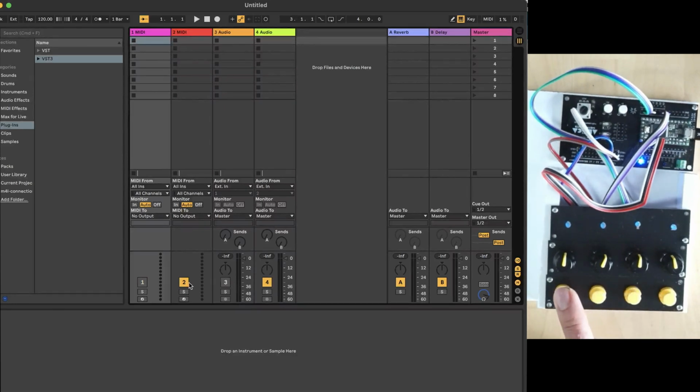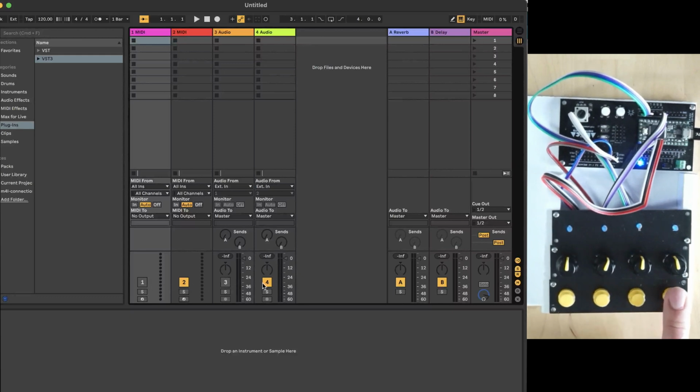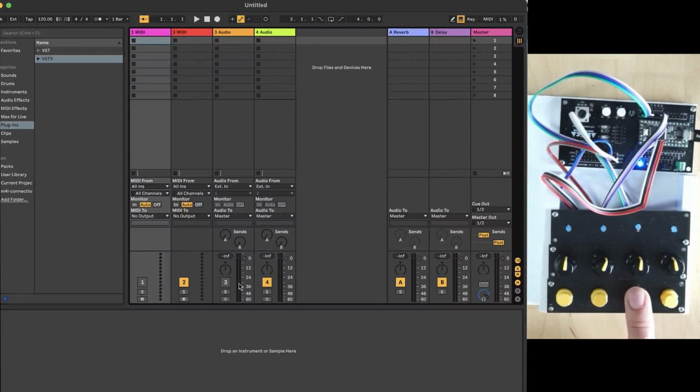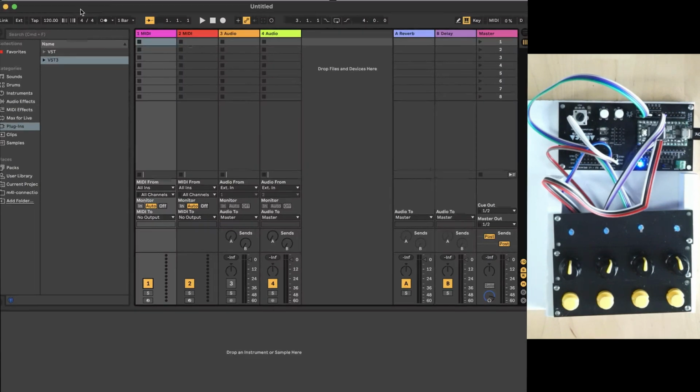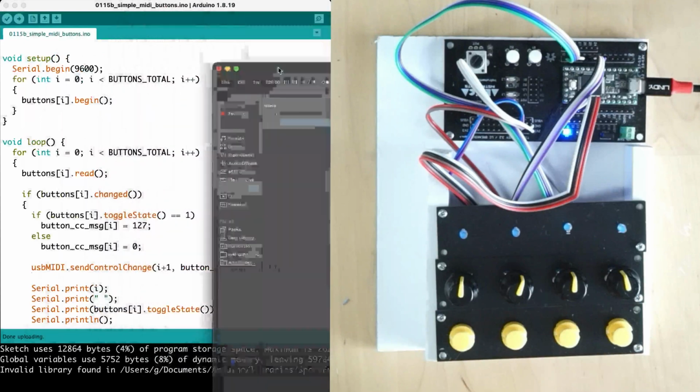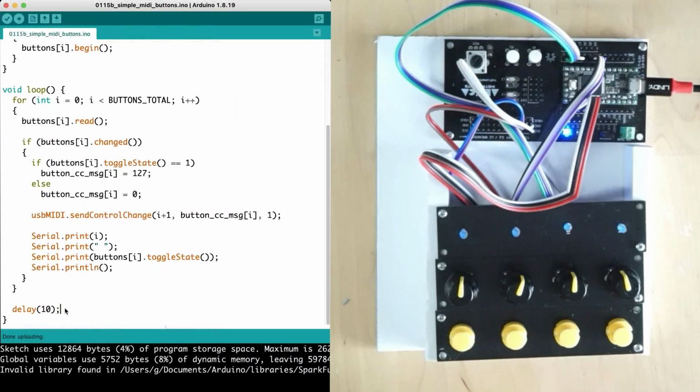And now we can see that I'm still pressing, but there's something going on because it doesn't give the feedback that we want. This is the mouse, but the MIDI is not going through anymore, and this is probably because there is some buffer overload, and I don't know if it's on the Ableton side or on the Teensy side, but there is a quick fix for this, which is while USB MIDI read.